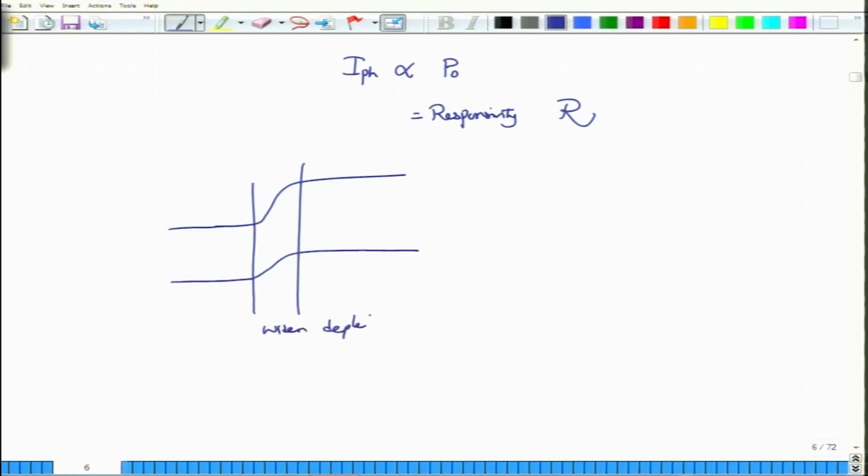So, when you widen the depletion layer and then create an electron and hole pair here by shining light onto this depletion layer, because this is N type region and this is P type region, there is a built-in electric field which is very strong, and it is strong because you have also increased the depletion layer and increased the reverse bias.